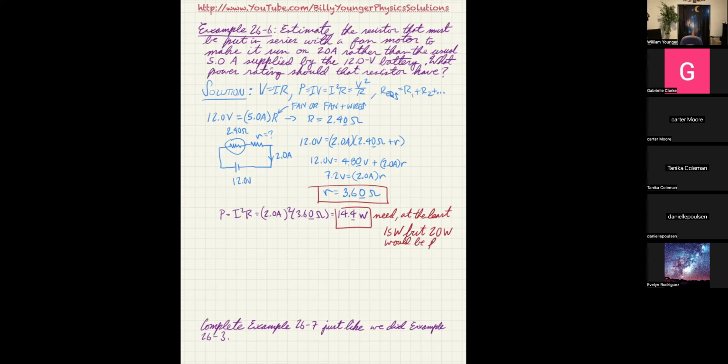Now remember, basically, when you start motors and stuff like that, there's a little period for them to get hotter and hotter. So when they get hotter, the resistance gets higher, which means when they first start up, the resistance is going to be low, so you're going to draw a buttload of current. So you don't necessarily want to design for just 2 amps. You want to design for a little bit bigger than 2 amps. In fact, if the cost wasn't prohibitive, I would jump even as far as 25 watts. But anybody have any questions on that one?